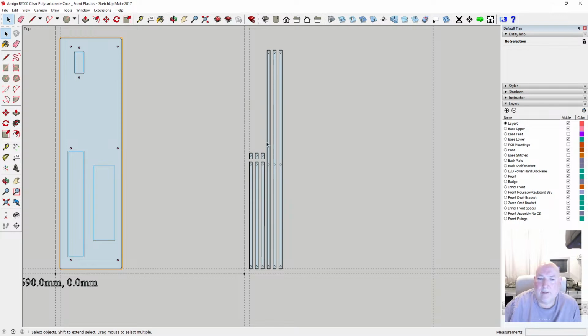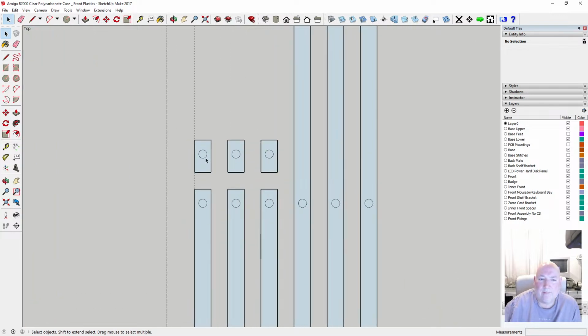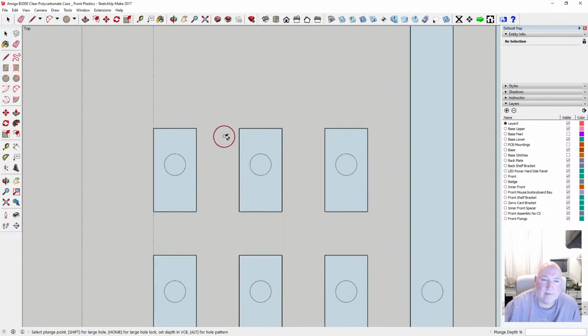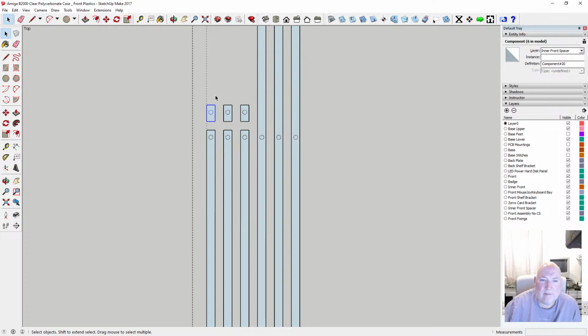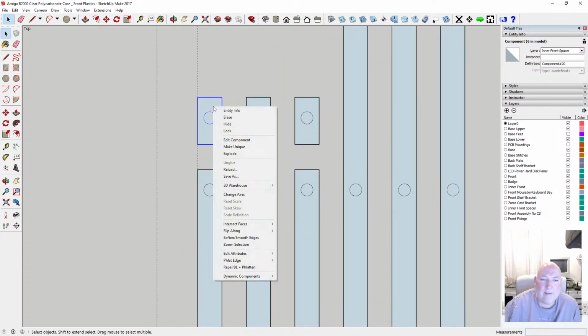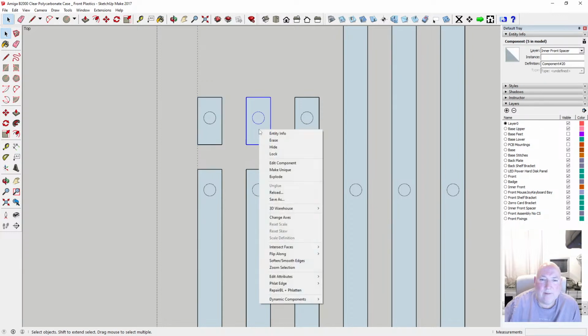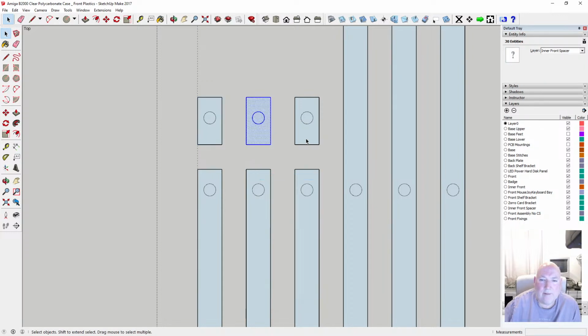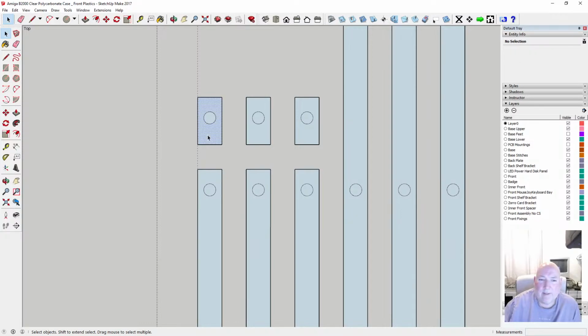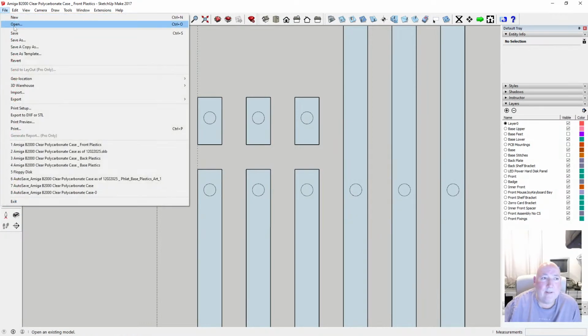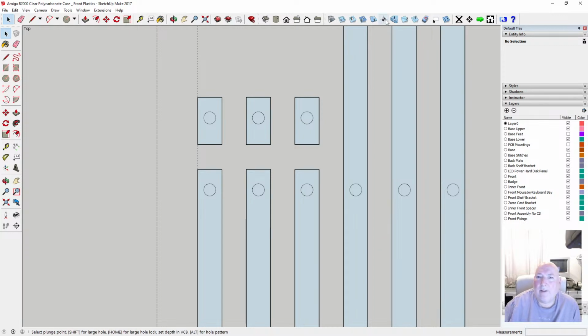So let's just do some code then. We want some plunges. Plunges first. Oh, I can't do it like that, we've got to explode them all. How do we do that? Right. Explode. Can I just select more than one and explode the lot? Maybe. Can you? Yeah. Okay, so we've got them like that. So I can now go ahead and plunge the lot.